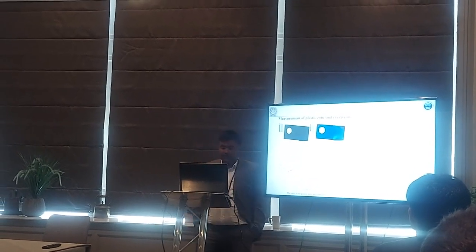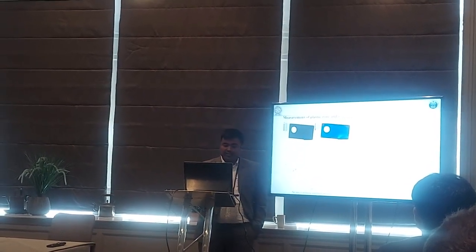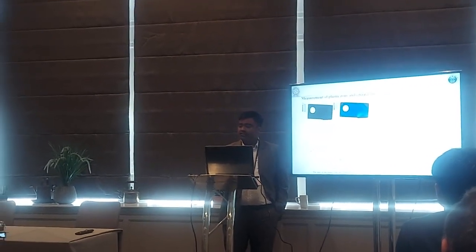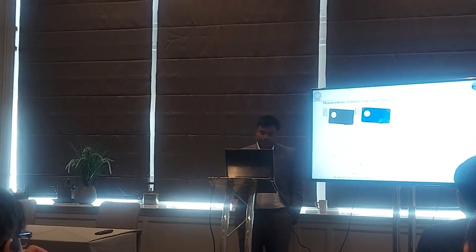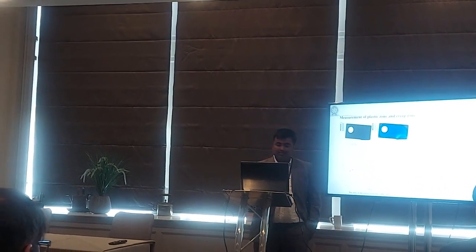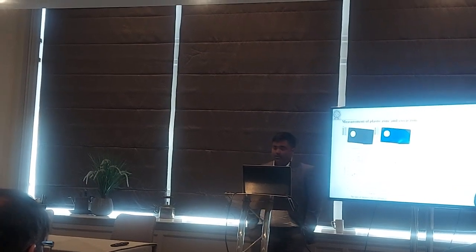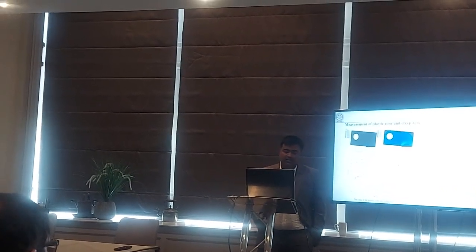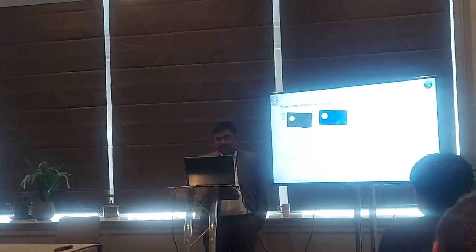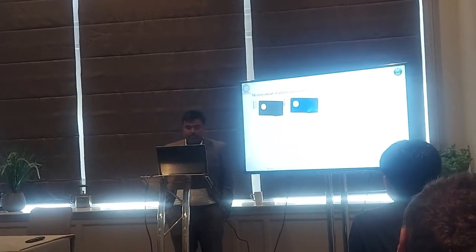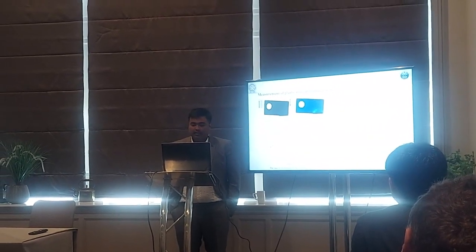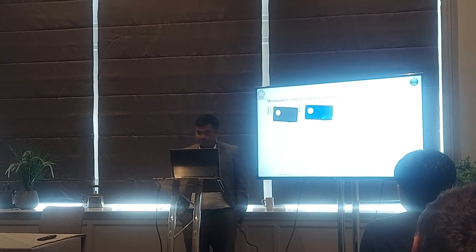It shows that the creep zone size is very highly dominant, and the plastic zone size is very small. This is consistent with the analytical expression given by Ashok Saxena. The theoretical creep zone size is in between this, and the result shows the domination of creep zone size for this material.